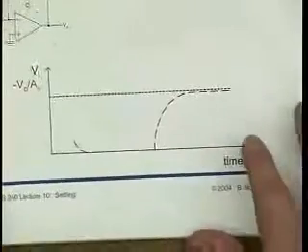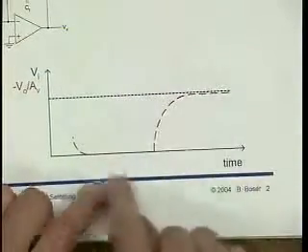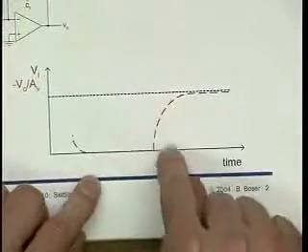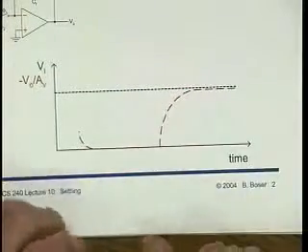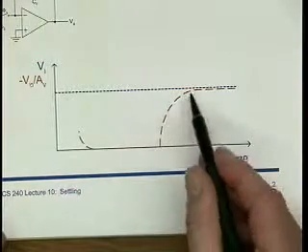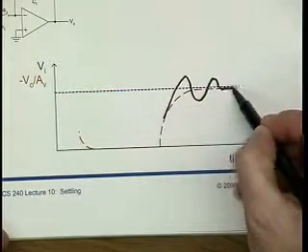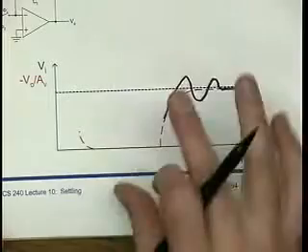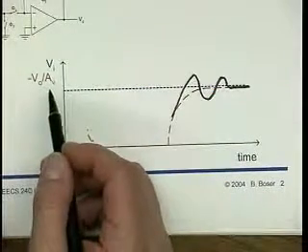So this is sort of what it's going to look like. This didn't come out of SPICE, so it looks like a PowerPoint. Right? But there is really going to be two things. One of them, it takes some time, and of course it could even be ringing, hopefully decaying ringing, of a circuit that doesn't have 90 degrees of phase margin.